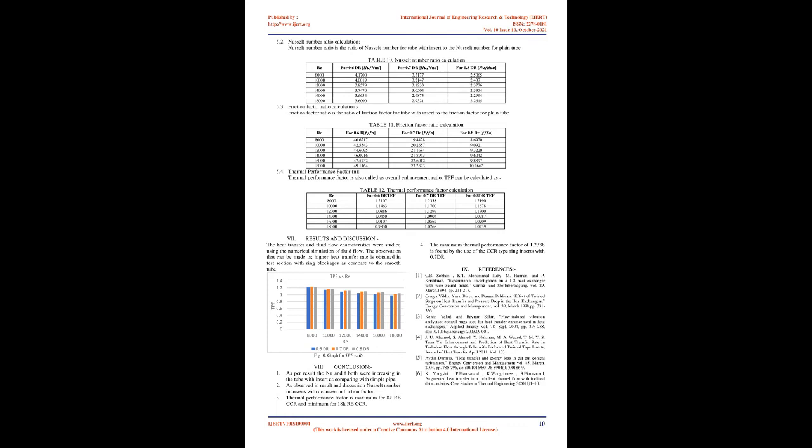Meshing of the domain is done using ANSYS software. The computational domain was discretized using tetrahedral elements of different sizes. In order to resolve the flow near the wall accurately, prism layers were added. As can be referred to above, a tabular representation of the grid independency test was conducted for the CCR geometry, and all readings are within the standard range.